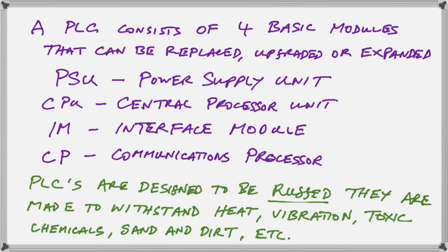Now, the PLCs, above all else, are designed to be rugged, depending on where they're being used. But typically, they're going to withstand more heat, vibration, chemicals, sand, dirt, etc. And they involve military-grade electronics chips that are able to handle a wider temperature range, greater noise immunity, and all that sort of stuff is built into your PLC, which makes them rather expensive, even though they look rather simple. A lot of the money is spent in ensuring that the electronics is protected from the environment in which it is going to be used.